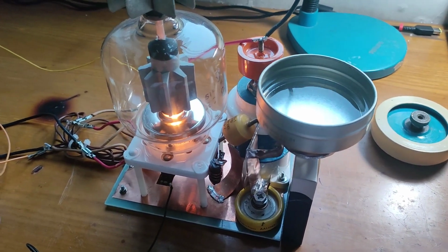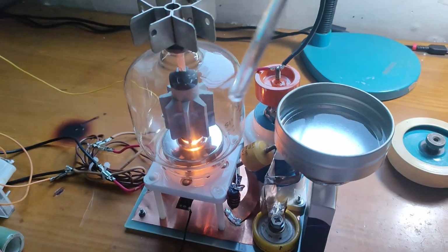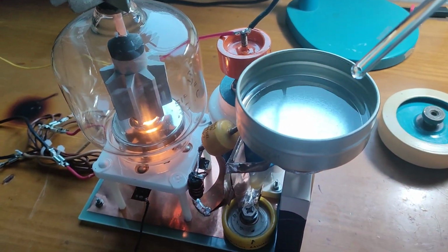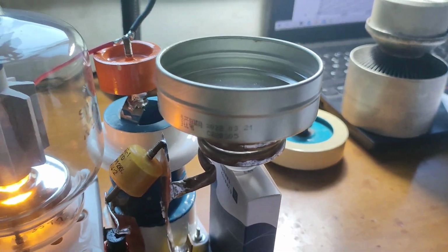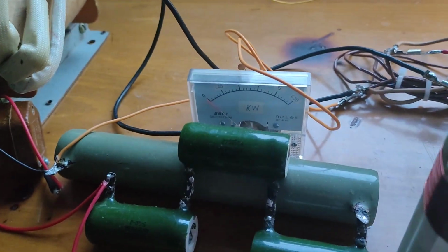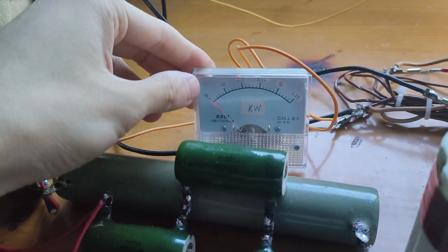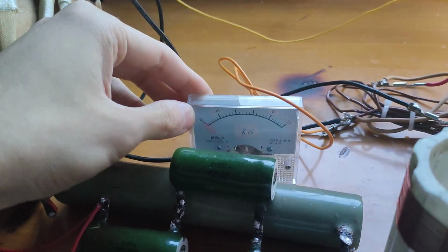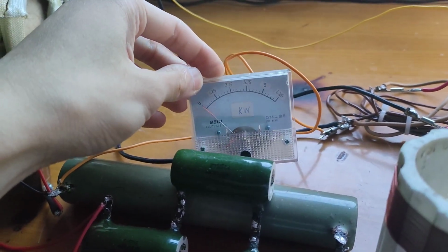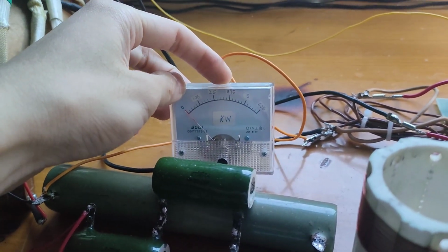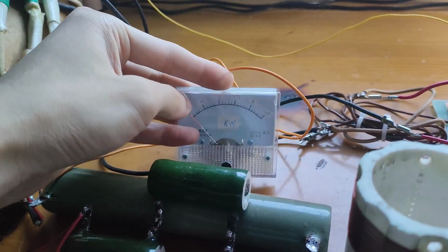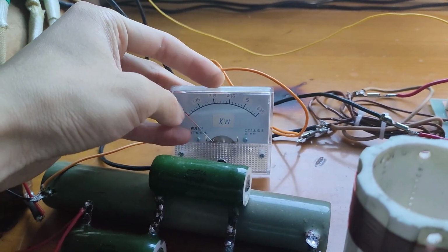First, please let me make a brief introduction of the whole setup. The RF generator, a plate of water which is my dummy load. As you can see, the induction coil is magnetically coupled with the plate of water. The cooling fan is in operation. This is my grid current meter. The original meter I used yesterday was burned due to the RF, and this time I just tore this meter down from another device I made, and the fourth scale means 1.6 amps. So each of the small scales means around 66 milliamps.